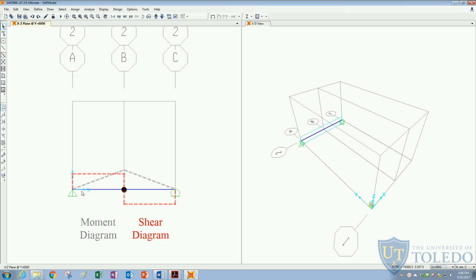So we know that the moment diagram is maximum in the middle, and the shear diagram is maximum from the support to the center, and in the center it changes side and it's constant up to the other support. So here at this section we will have both higher moments and higher shear. In contrast to this shear hinge, we will only have high shear and low moment.